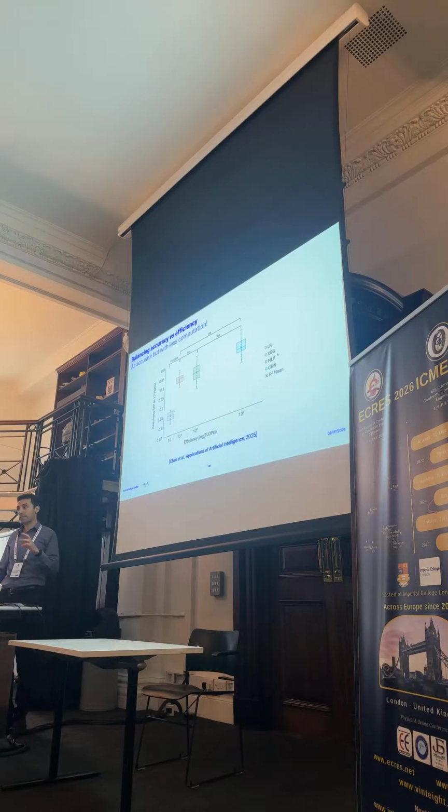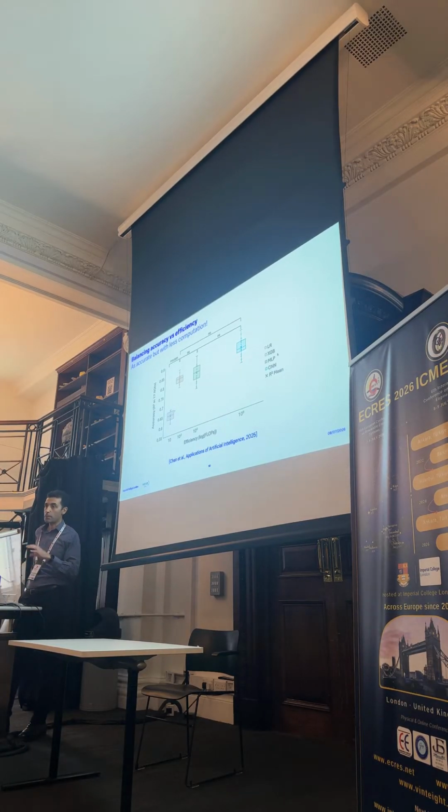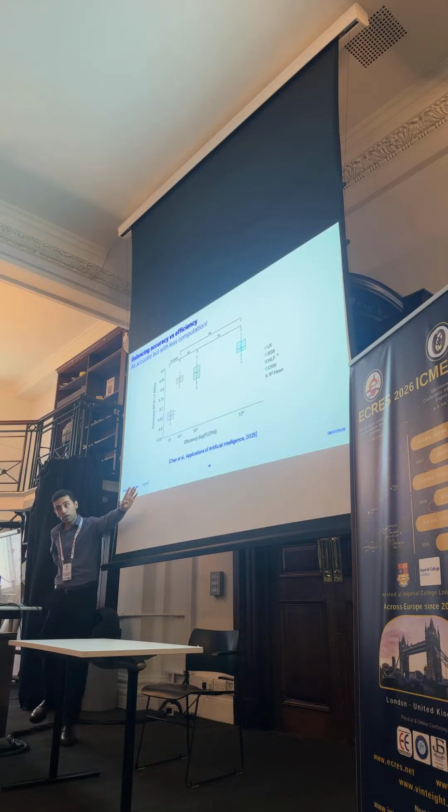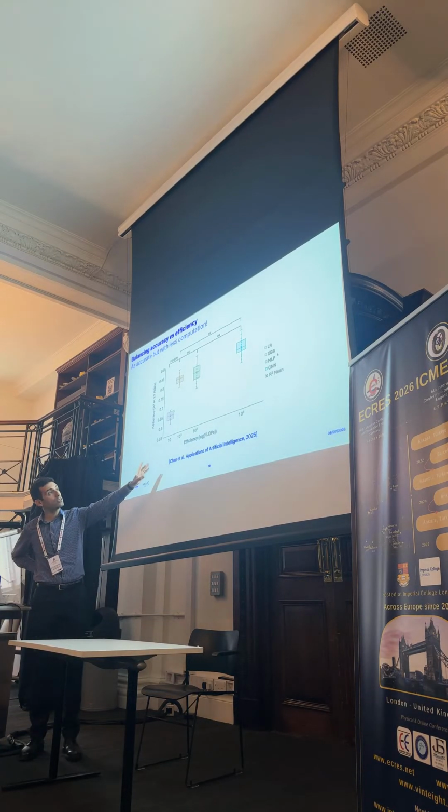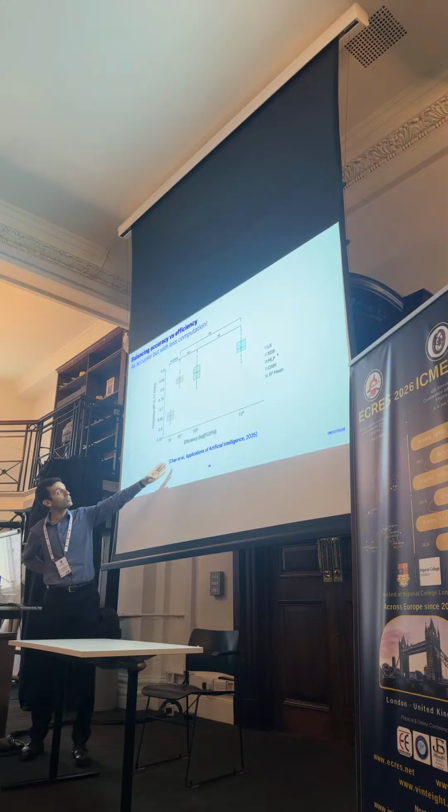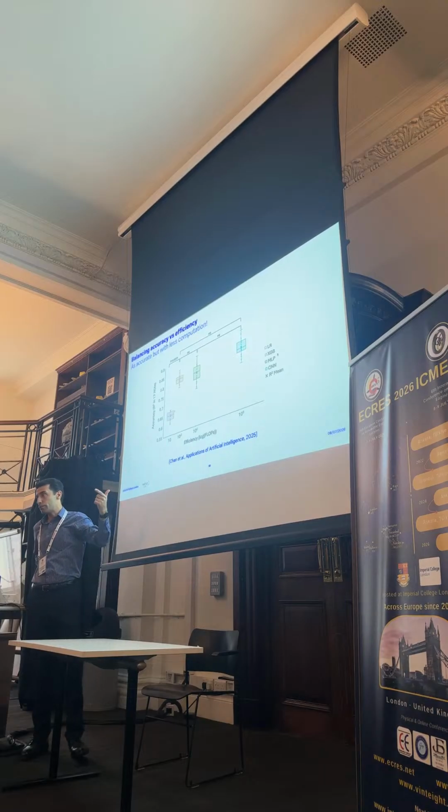One thing we found is that we have to make the computation as light as possible on the mouthguard chip. That's why we found that using a CNN, convolutional neural network, may not be the best option. If you look at FLOPs, floating point operations, the number of FLOPs with our XGBoost model is around 1,000, but with the CNN it is orders of magnitude bigger. So it means that CNN is not really an efficient approach, while both of them give similar accuracy.